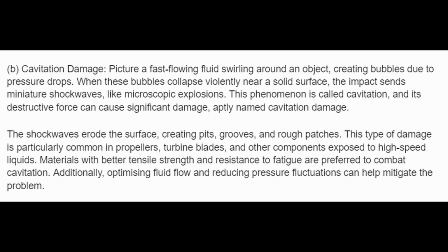This type of damage is particularly common in propellers, turbine blades, and other components exposed to high-speed liquids. Materials with better tensile strength and resistance to fatigue are preferred to combat cavitation. Additionally, optimizing fluid flow and reducing pressure fluctuations can help mitigate the problem.